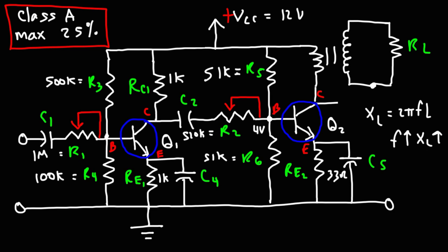So there's more impedance towards high frequency AC signals. Now, because the DC resistance of inductors tends to be low, RC, in this case RC2, which you could think of as the DC resistance of that inductor, because it's low, that's going to increase the current gain of the circuit. So that means we can get a larger collector current flowing through Q2.